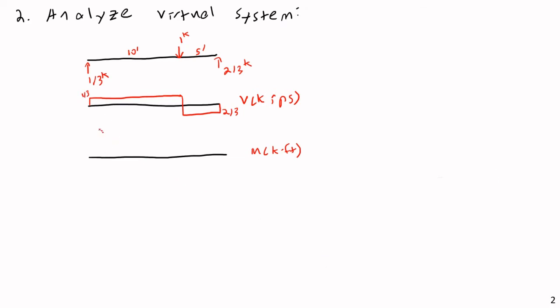So we have our loading and we have our shear, and now let's again use the area method to find our moment. The area of this, the height is 1/3, the width is 10, so we're going to be up to 3.333, or 10 over 3. Again, we're starting at 0 on the moment because this is a pin support. The area of this is positive 10 over 3, so we're going to increase from 0 by 10 over 3, ending up right at 10/3.